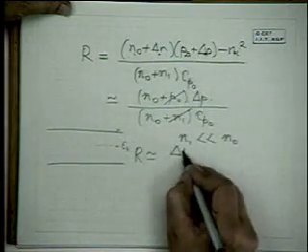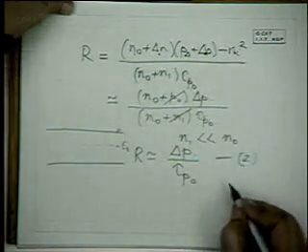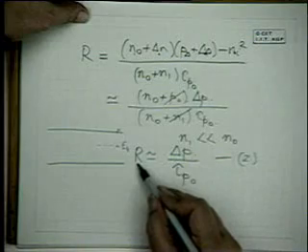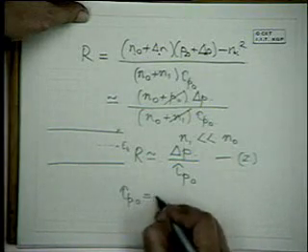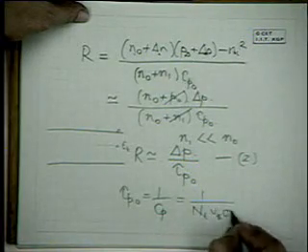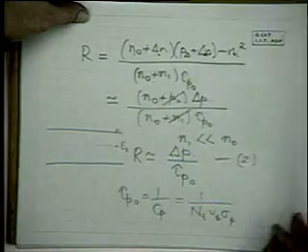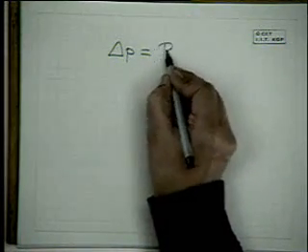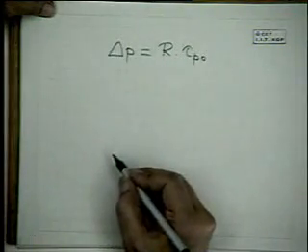So we have the simplified expression that is very often used, that for an n-type semiconductor, the minority carrier lifetime being tau p0, the recombination rate is just delta p by tau p0. Okay? Where tau p0 is 1 by Cp is 1 by Nt V thermal sigma p. Or if we want to rewrite this, we often can say that the excess minority carrier is the recombination rate into tau p0. Okay. So this is for n-type materials.